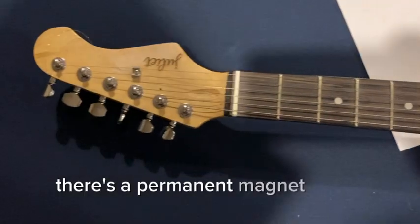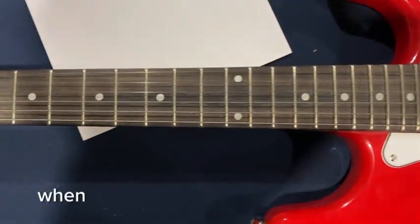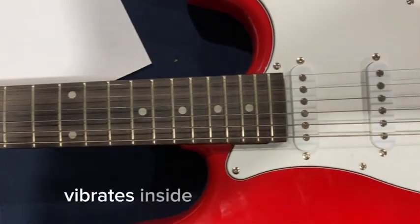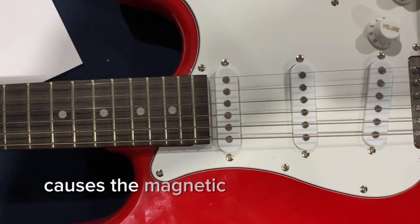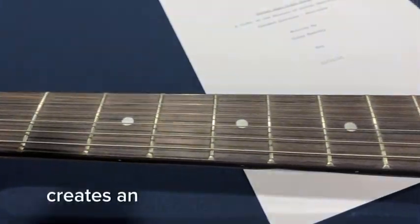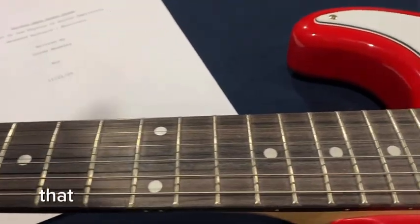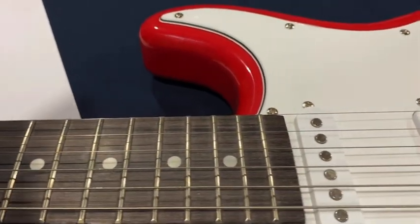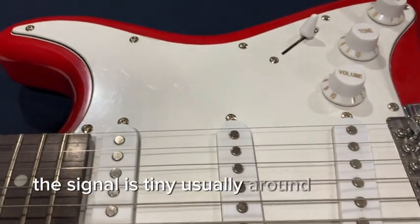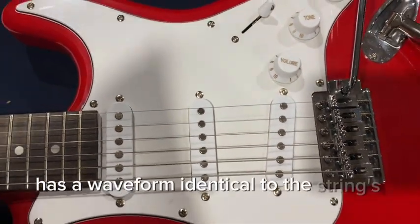There's a permanent magnet in the pickups, with coils of copper wire wrapped around it. When the string, which is made of metal, vibrates inside the magnetic field, it causes the magnetic flux through the copper to change. The changing magnetic field creates an electric current in the wire. The result is an alternating current that matches the vibration of the string. The signal is tiny, usually around 50 to 100 millivolts, and has a waveform identical to the string's motion.